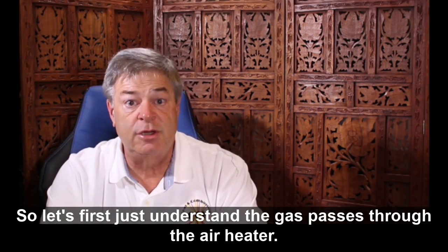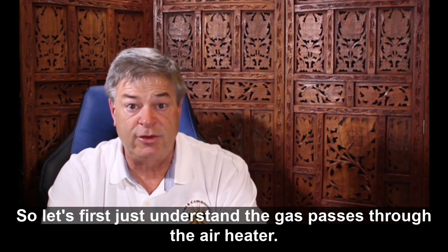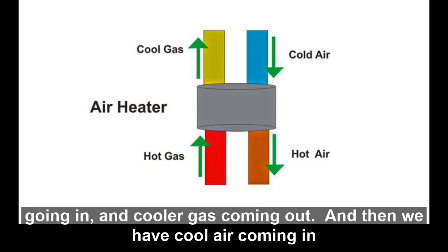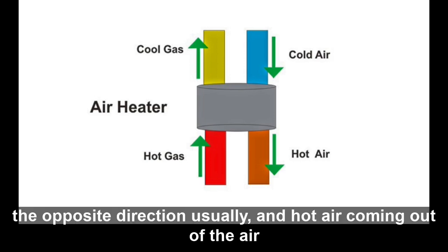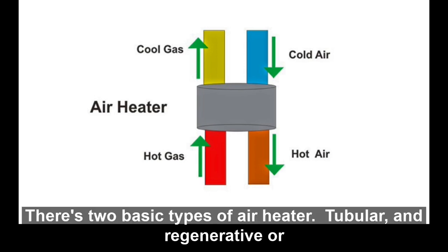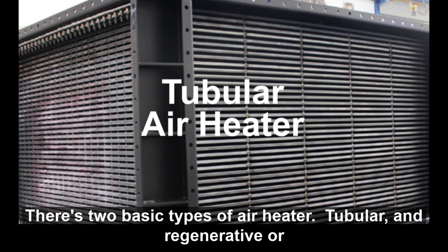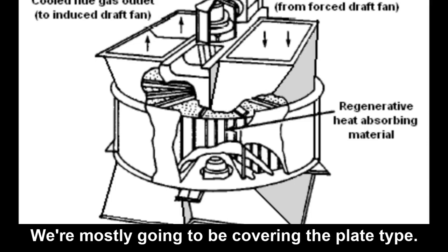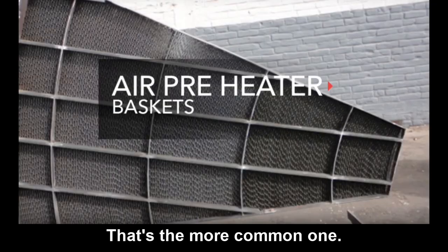So let's first just understand the gas passes through the air heater. So we have hot gas going in and cooler gas coming out. And then we have cool air coming in, going in the opposite direction usually, and hot air coming out of the air heater. There are 2 basic types of air heater, a tubular and a regenerative or plate type. We're mostly going to be covering the plate type. That's the more common one.